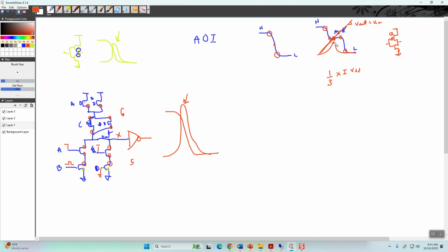So now the advantage of these, in this case, tri-state logic is, well, you can fit more data per line, right? So more data per line means less lines, means less off-chip communication, which reduces power. That's a lot of advantages for reducing power. But 1/3 of the time, on average, right, you're going to be here, burning a lot of power. Now, there's a way around that too.